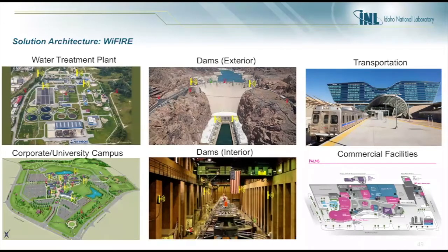First example, at one facility, some equipment suddenly failed to function properly. The incident occurred over several days, and in the absence of a spectrum monitoring capability, all that could be initially determined was that the equipment was malfunctioning intermittently. Eventually, after several days, the RF team was able to identify the frequency and the two people causing the incident. They were both contractors using handheld, unlicensed band radios, which interfered with the operation of the facility.